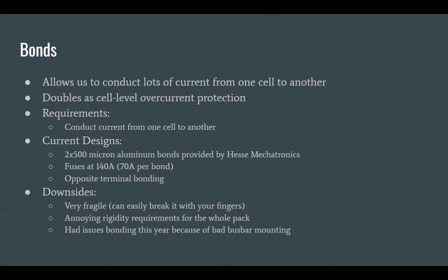We did mention briefly last time that the current problem is that we do have the battery cells, but the complexity, cost, time, and effort that would go into making more cell holders is quite high. So if we did have one or more bonds break, the plan is that we're going to bring something like a thin nickel strip to competition, and then use a spot welder to spot weld that on in place of the bond.